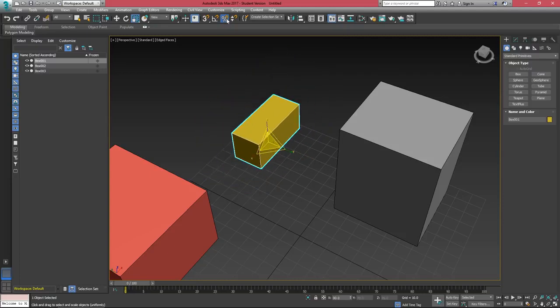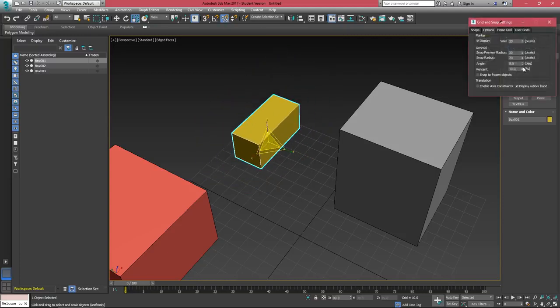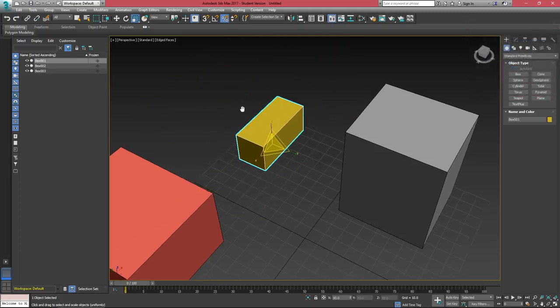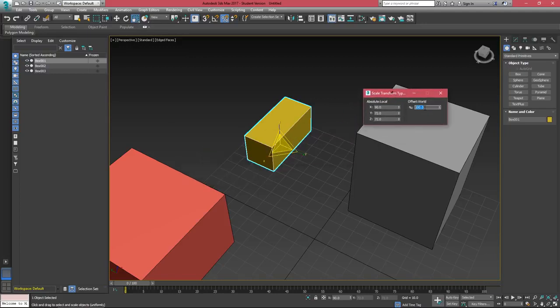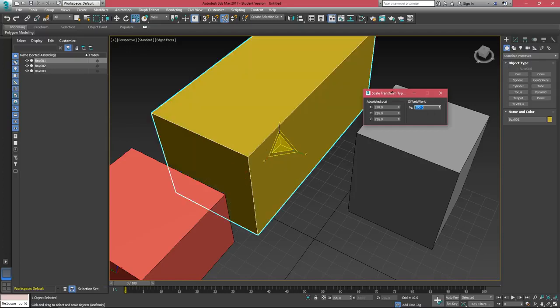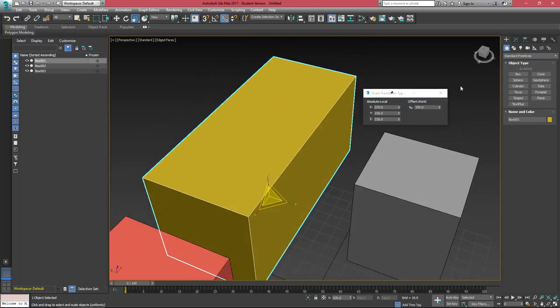I actually don't use this one that often, but you can turn the percent up or down here so we can snap to 50% increases if we'd like. I personally find it easier when I'm trying to scale if I right-click on the scale dialog, and I can just give it the scale percent here. So if I want 300%, I can just type that in and hit enter. I find that much easier than kind of guessing for the angle.